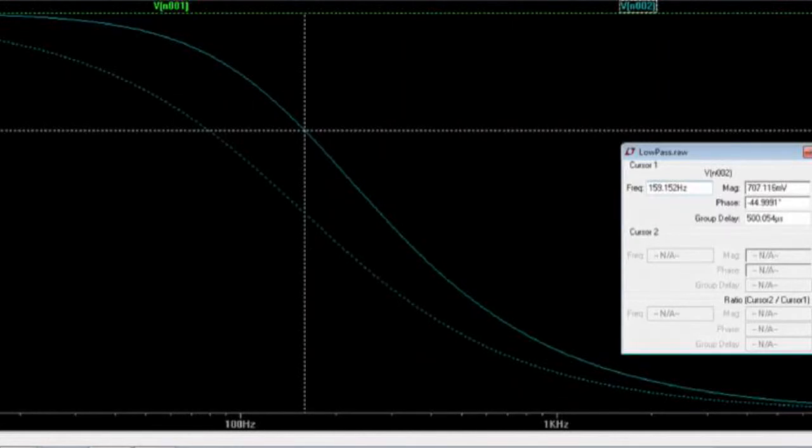We see that on the low-pass graph, at low frequencies the output is about the same as the input, 1 volt. Then as frequency gets higher and higher, the output drops to about 0. We calculated omega naught to be 1 kHz, so we expect the voltage to be 1 over the square root of 2, or 0.707 at the 1 kHz mark.